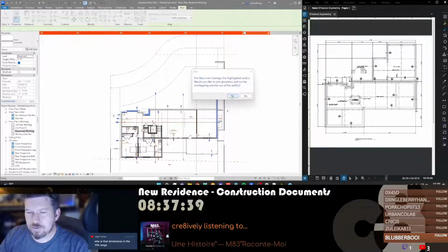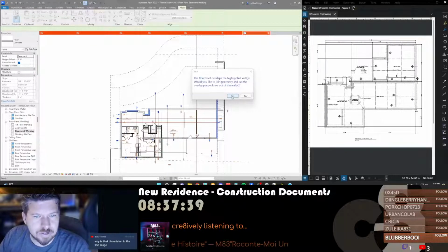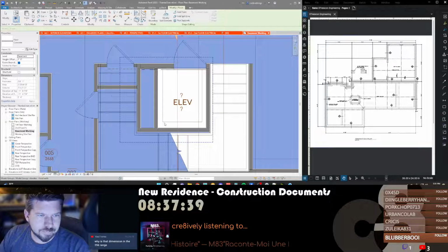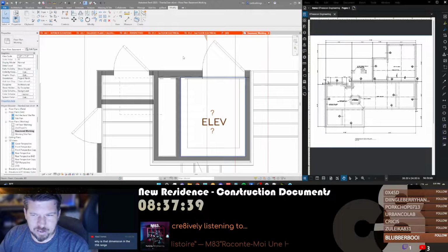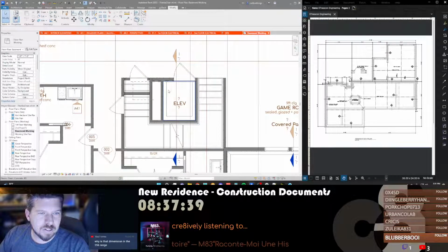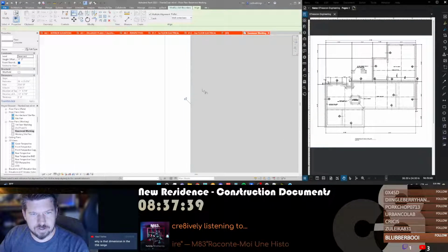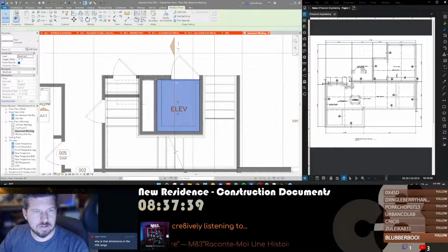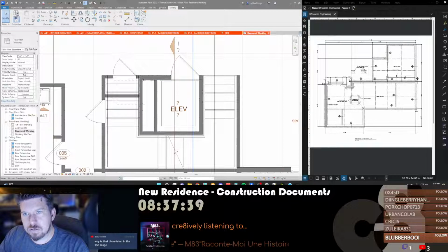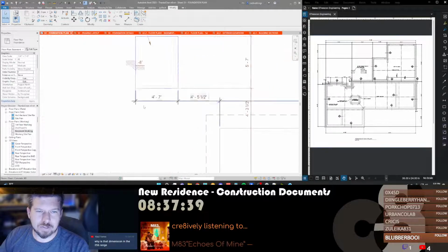That dimension is in the 256 range so that I know that something is off. I intentionally set all of my dimensions to the 1/256 tolerance so that something like that jumps out at me and I don't have dimensional errors. That's why I've been staring at these same drawings for the last 15 minutes trying to figure out what's going on. And now that I know what happened, I've got it fixed. The dimensions should be correct now. Let's see. Yep, there we go. That's accurate.